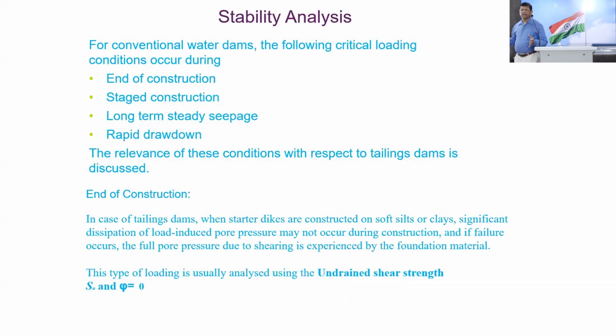Again, the conceptual stability analysis. Everything started from the hydro dam, that's why I am showing the hydro dam here. How do we analyze a hydro dam? We do end of construction. We also do stage construction. We also do long-term steady seepage after everything is done, and we also do rapid drawdown in case of the hydro dam.